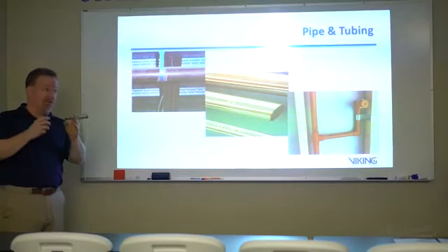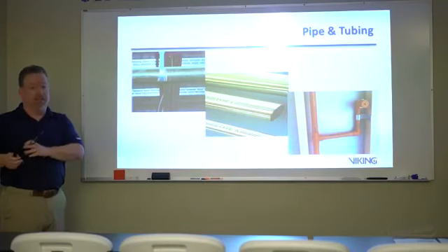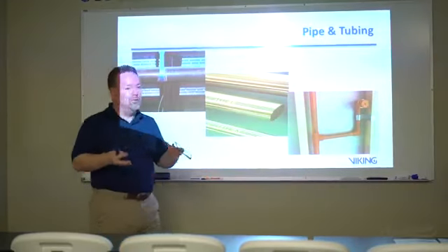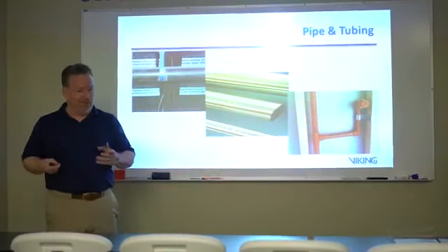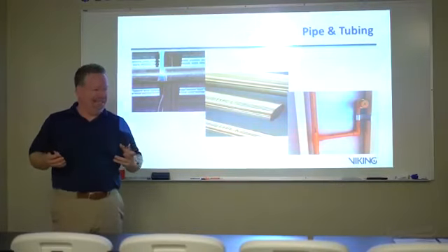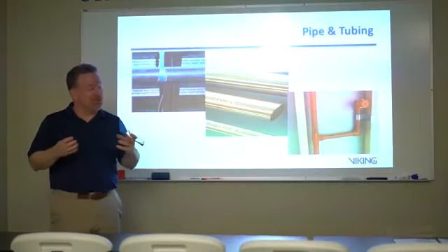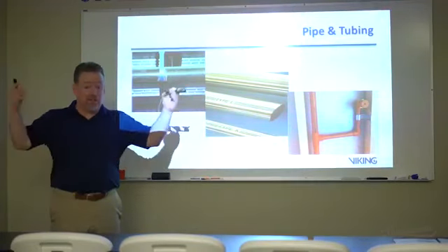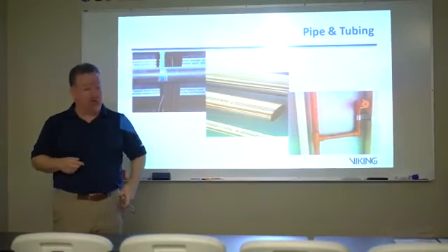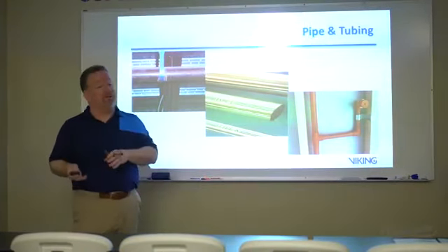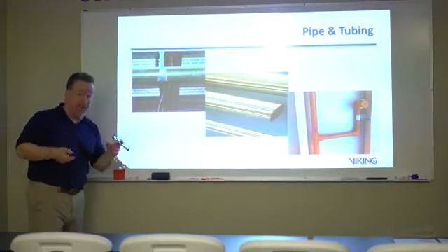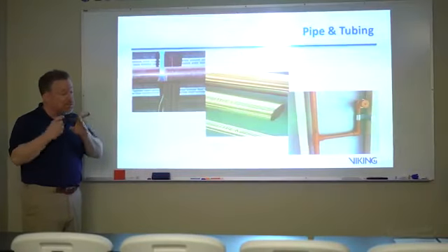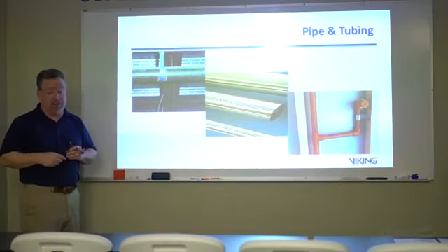it's magnetic resonance imaging. So the system itself, the MRI unit, when it's operating, what does it do? It becomes a magnet. And if you've got anything in your sprinkler system or in your sprinkler that is attracted by that, it will eventually go towards the unit. So you have to use very specialized MRI type sprinklers. We have a few of those that are listed for use with MRIs. So that's a real specialized area you have to be very careful of when you're putting that in.